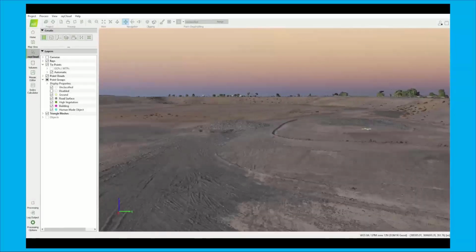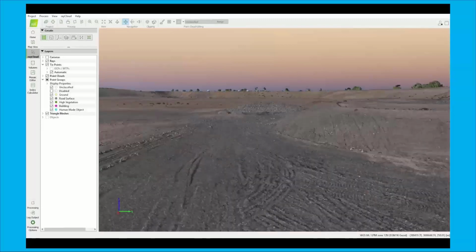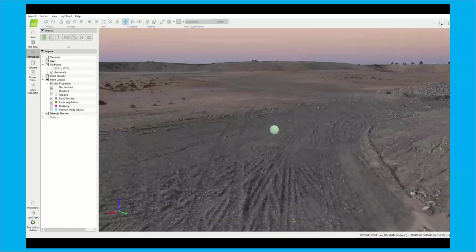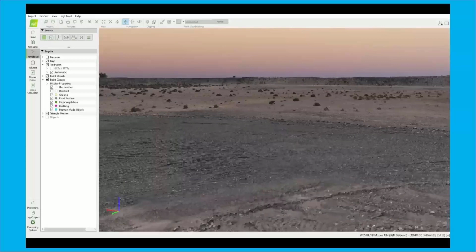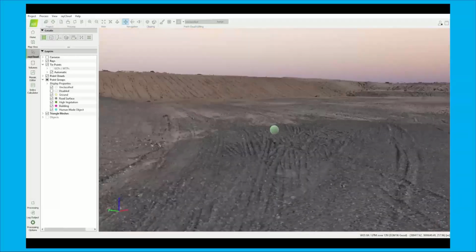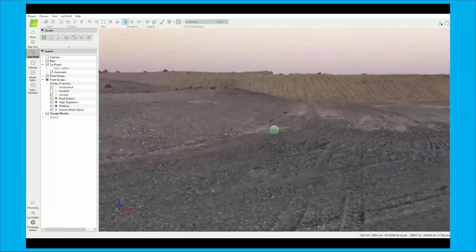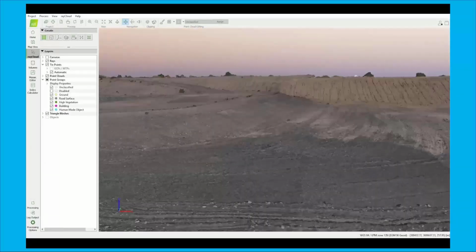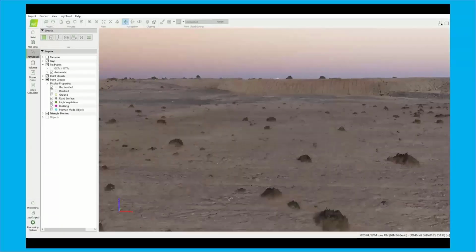The flying altitude here, probably anywhere between 350 and 400. We typically set flight plans at 390 feet AGL, and we take off and land vertically. So with terrain following, we're maintaining that 390 plus or minus 10 feet throughout the entire flight plan.